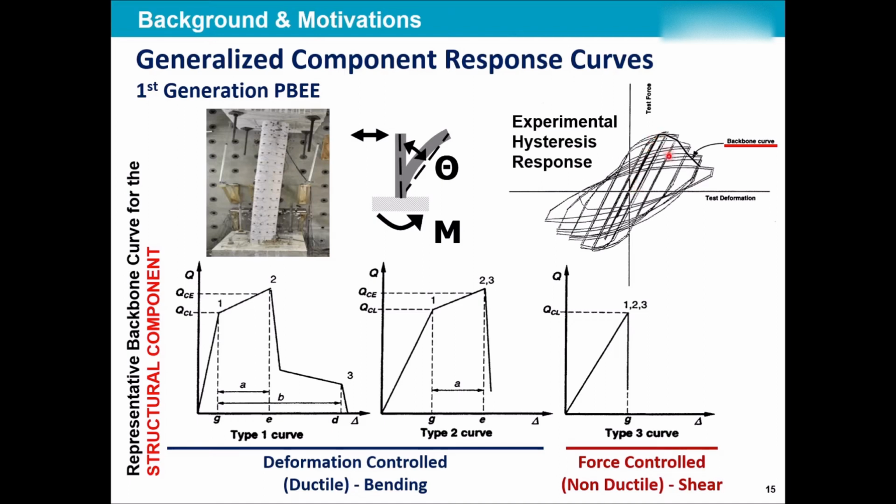They were getting from a hysteresis, which is a push and pull, let's say tension compression behavior, just the monotonic curve that we discussed before as well, just one representative in, for example, the tension side. And this is the curve. Now imagine that you have a curve for every single possible component characteristic of a reinforced concrete. After a while you can see trends, so they started giving values for each bit.